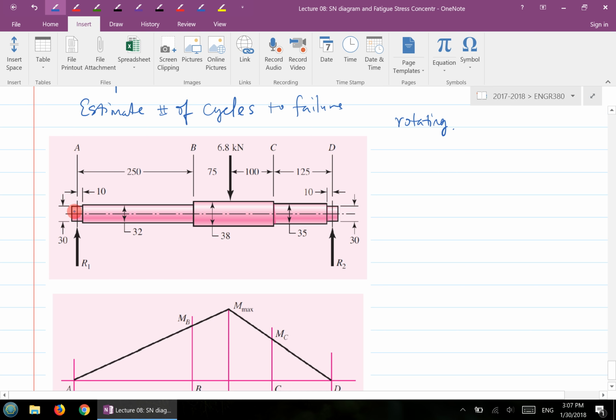There are a number of step locations. So later when we learn about shafts, one thing that we're going to learn is that the structure of the shaft is a stepped shaft with shoulders. There's a stepping up, and the shoulder location will be used to locate or fixture certain elements on the shaft accurately.